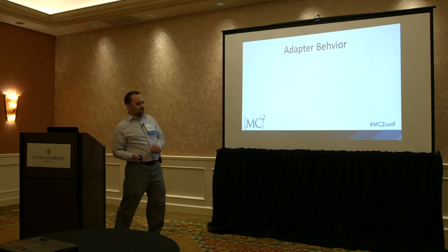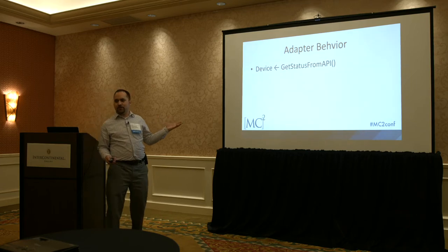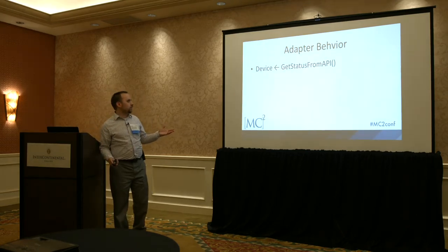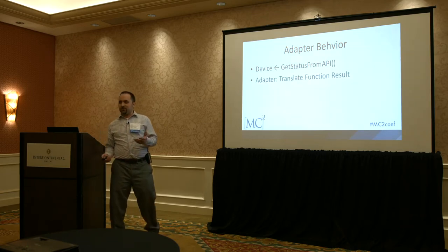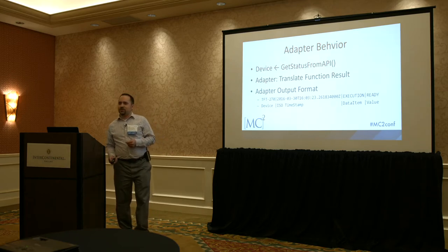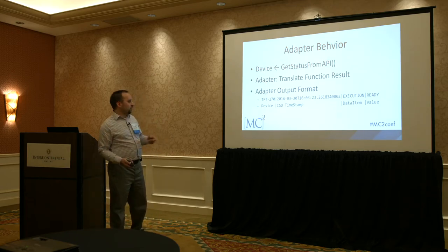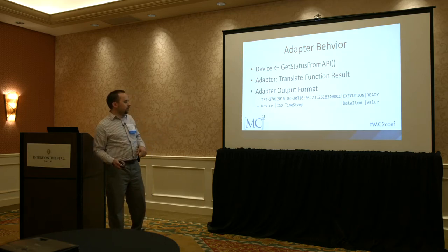So adapter behavior is, for example, we would have a device, we'd have an API command that interacts with that device. And so the adapter would be pulling data through this function. It would then translate the result of this function and output it in that SHDR format to the agent. And it's just a simple pipe-delimited format.